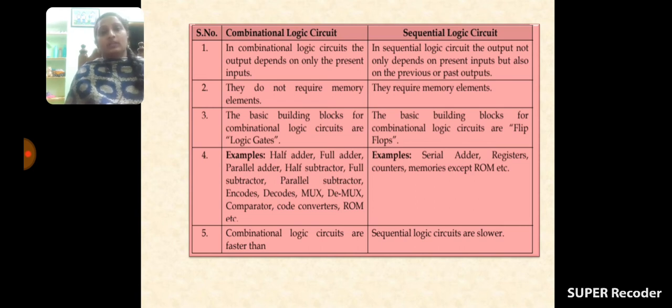To express the sum function, an exclusive OR gate is used, and to develop the carry function, an AND gate is used. Likewise, a full adder requires 2 half adders, meaning 2 exclusive OR gates, 2 AND gates, and 1 OR gate. Similarly, a parallel adder with n bits requires n number of full adders, inside which are gates only.